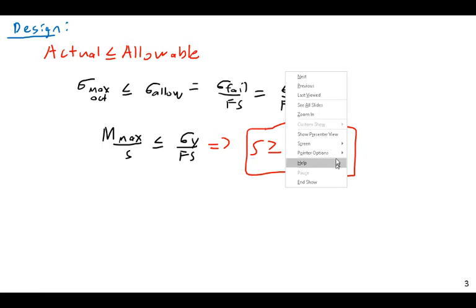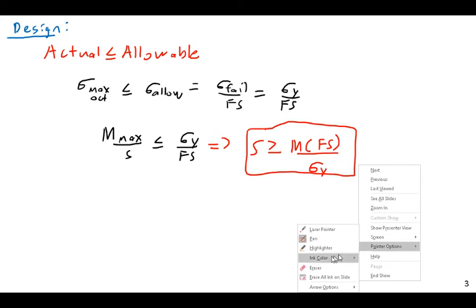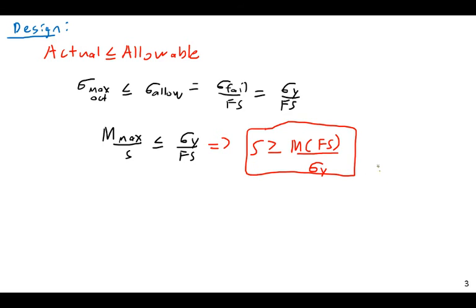Okay, so how do we find the cross-section? How do we find the cross-sectional properties? Well, you can either calculate them yourself, simply by calculating I, or more often, you'll actually have a table of selected shapes. For example, you can get them from the beam table, select beam shapes from Appendix B, page 804 in the Hibbeler text.